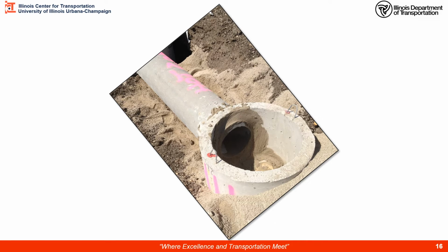So again, to illustrate a little bit about the trench backfill, this is the area where the trench backfill will be paid for up to the inlet structure. Remember, we got 6-inch diameter that will be included in this structure. Or if you cut that in half to a radius, is 3 inches. So on our trench backfill, we need to subtract off that 3 inches on this side, because that 3 inches is included in the cost of this structure. So minor detail, a little bit of math, but that's the way the specification is conducted.